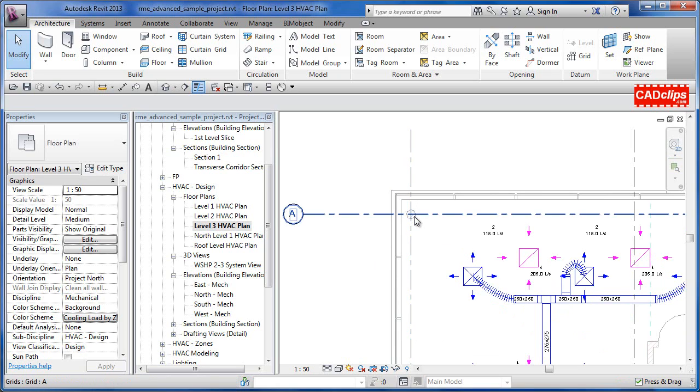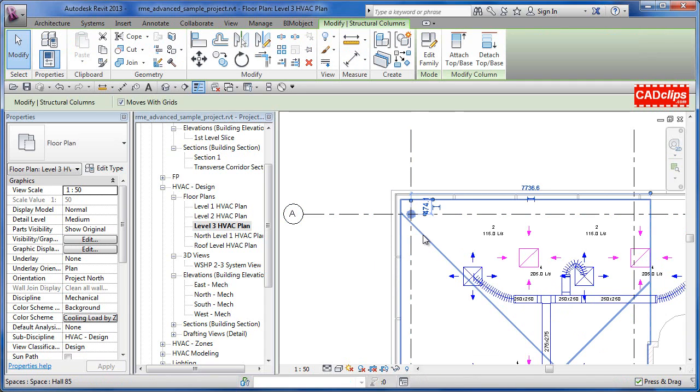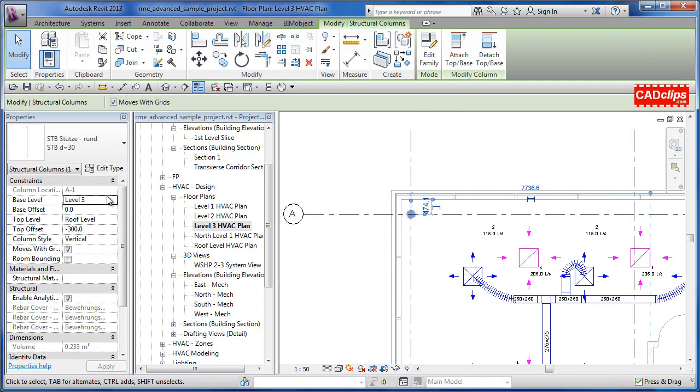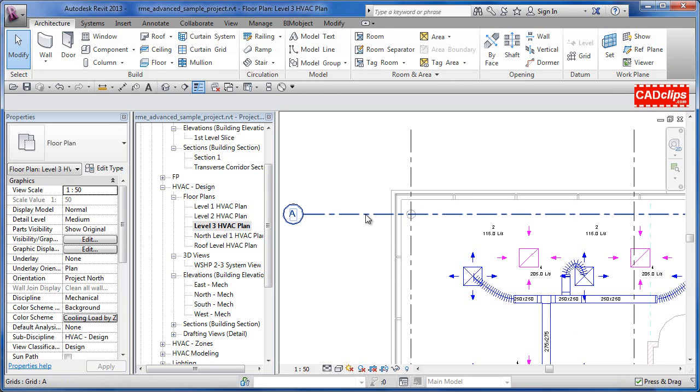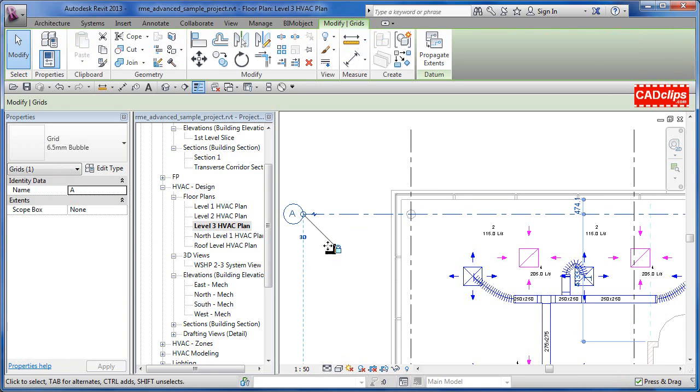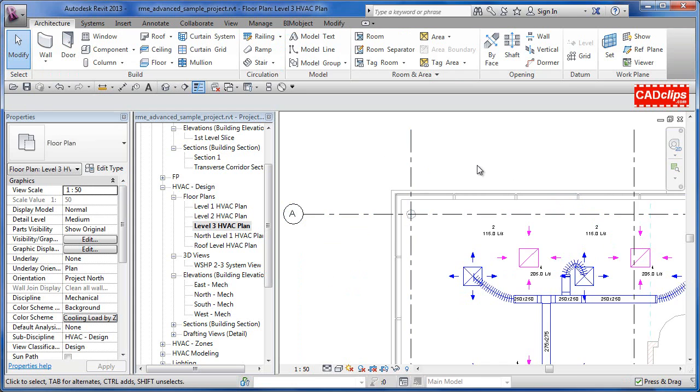However, if you pick on the column, and I'm going to use my tab button because it's too busy, see, tab on the keyboard, click, and I pick on it and it shows me the properties. It's definitely going to show me the base and top of the column location. So grid lines, we will go into more detail about controlling them. Notice you get these wonderful little temporary dimensions. Whenever you pick an object, it'll show you some temporary dimensions, and we'll talk about that as well.